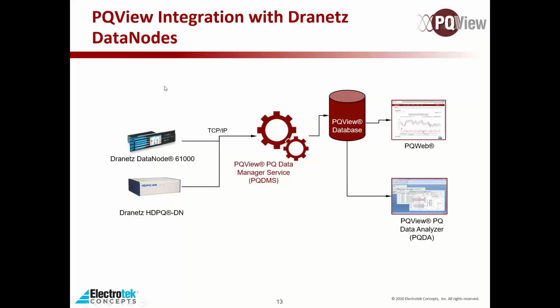Here, showing the integration with Dranetz DataNodes. With Dranetz devices, we can actually both communicate with them and also do configuration on the Dranetz devices. So PQDMS is actually the software that's used to configure Dranetz devices, setting triggers and what data is going to be collected, all that. This is a nice straightforward setup, just talk directly from the DataNodes to the PQDMS, to the PQView database, and then you can use our analysis tools on it.